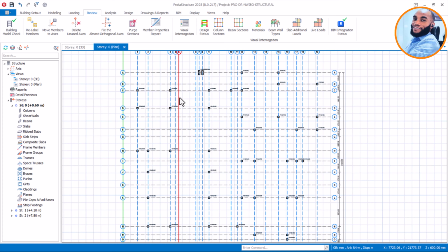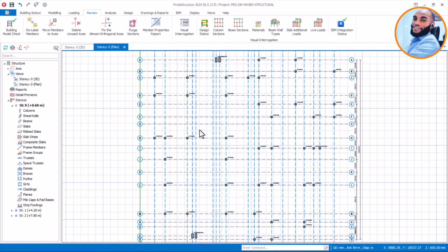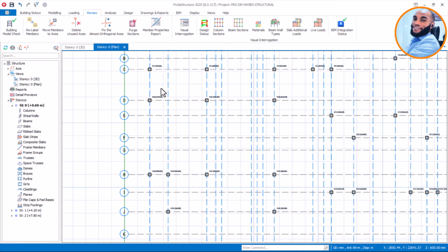So knowing that we have a beam and a footing, we are going to model our beam here as if we are modeling a beam raft. But there is a difference between beam raft and wide strip foundation. Beam raft has a deeper depth of beam, while wide strip foundation has a smaller depth of beam. Not that small, but smaller.